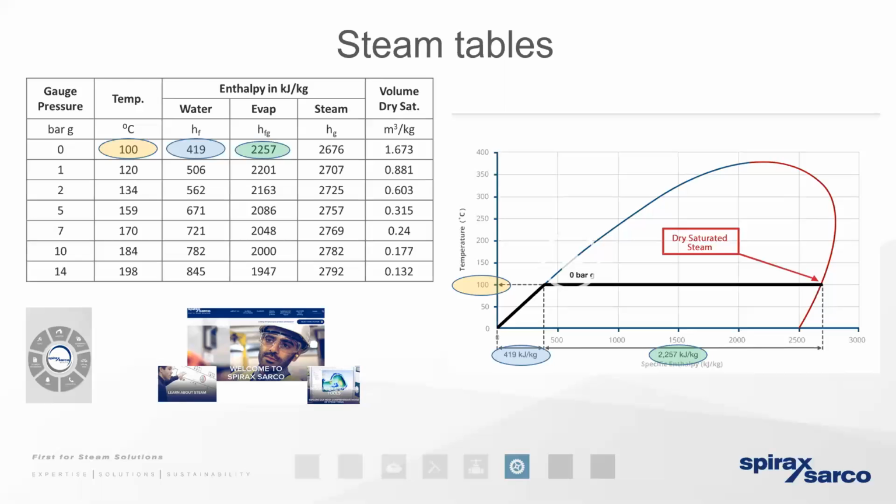So we've also spoken about the temperature enthalpy curve previously as well, and this really demonstrates the journey that water takes as it changes state from a liquid to steam as a gas. And we've emphasized previously that if we're generating wet steam in the boiler house, we expect to have a number of different issues. First of all, wet steam, as it travels around the distribution network, is far more likely to change state to condensate.